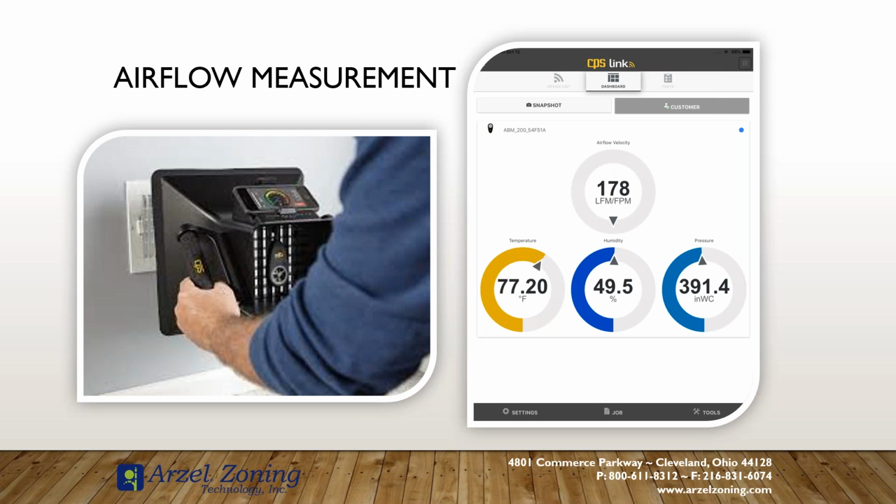So now I know that that register is underperforming, and I need to take a look at balancing out my ductwork or installing zoning, because maybe my ductwork's oversized, or maybe I'm pushing far in excess of that. And now my static pressure is high enough to the point where I can damage my equipment when I measure that out. So it gives us an indication of where our airflow is going, and knowing that, we can convert it to BTUs.